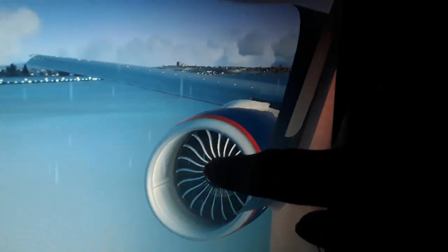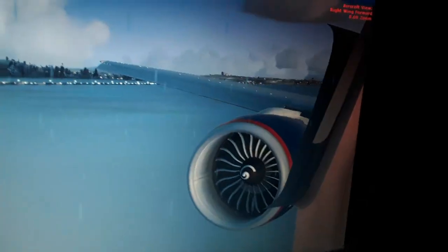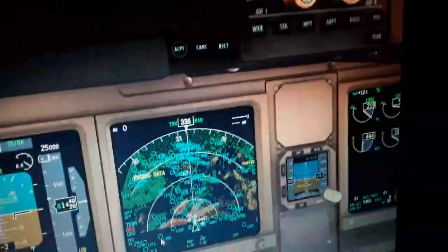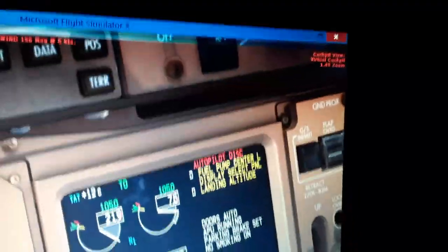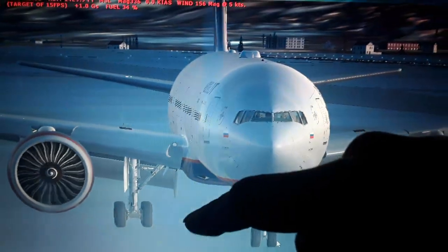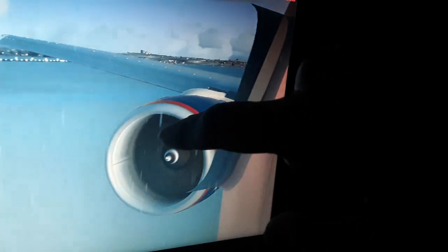So we go here in this view. Something is working out, but we still have no fuel, not much fuel displayed, 0. So we can here again start the fuel shutoff valve. We have like 30 more minutes for this flight, so we need to be very brief. So we start the right wing engine. You see the N1 and N2 increasing very rapidly. You can see the outside view also. We have the engine spinning. The right wing also. And here we go.